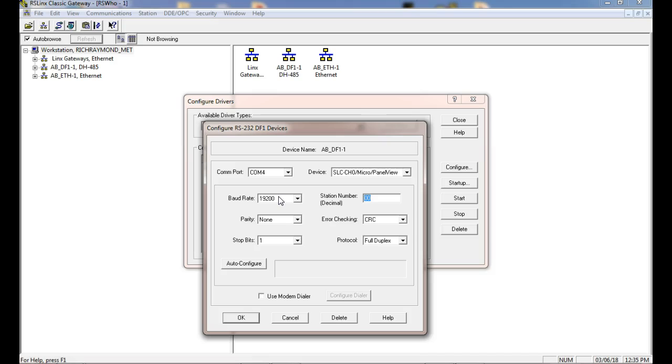So the carrier is what we do. What we're trying to do is send information through a media, and we want to send a lot of information through a media. How many channels do you have coming into your TV? How many cables do you have coming into your TV? How many channels are on that one cable? How do they do that? When I let multiple signals share the same media and the information travels through it at the same time, we call that multiplexing. If it wasn't for multiplexing, we'd be screwed.